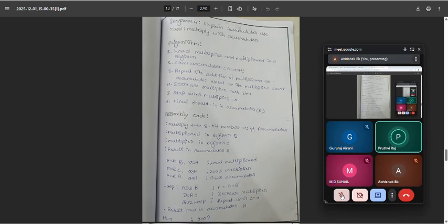My name is Prithvi. I am explaining program 4. It explains the accumulator, with the task of multiplying using the accumulator. First I will be explaining the algorithm. First, load the multiplier and multiplicand into registers. Second, clear the accumulator, A equals 00H.